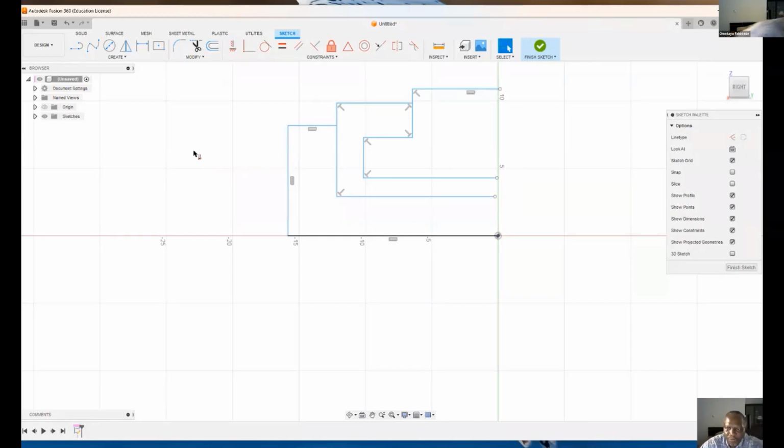So the next thing we're going to do is make sure that these lines are all along the vertical axis. To make them along the vertical axis, we can now choose horizontal vertical for the points. So if I take this one and this one, it forces these two to be vertical. Then we can take this one and this one, that is also vertical. If we take this one and this one, all of them are now vertical. So all these endpoints are right on the vertical axis.